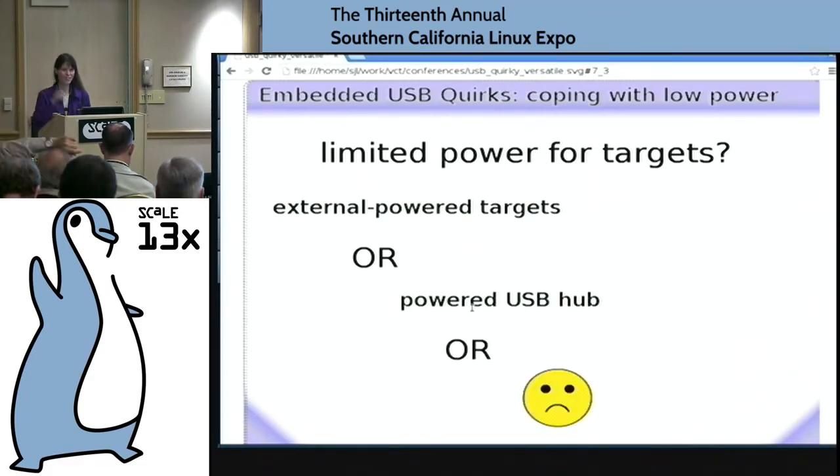And if neither of those apply... So a question: does the host controller have a power controller or a power regulator in it, or is it just power plus through the connector? It comes from the embedded board. It'll usually be a regulator that's shared by other stuff on the board. But if the board is mostly 3 volt, it might have a special boost just to provide the USB 5 volts. Because if it's just plus through, in theory, you could just put a power supply on it. Except the regulators don't always accept it.